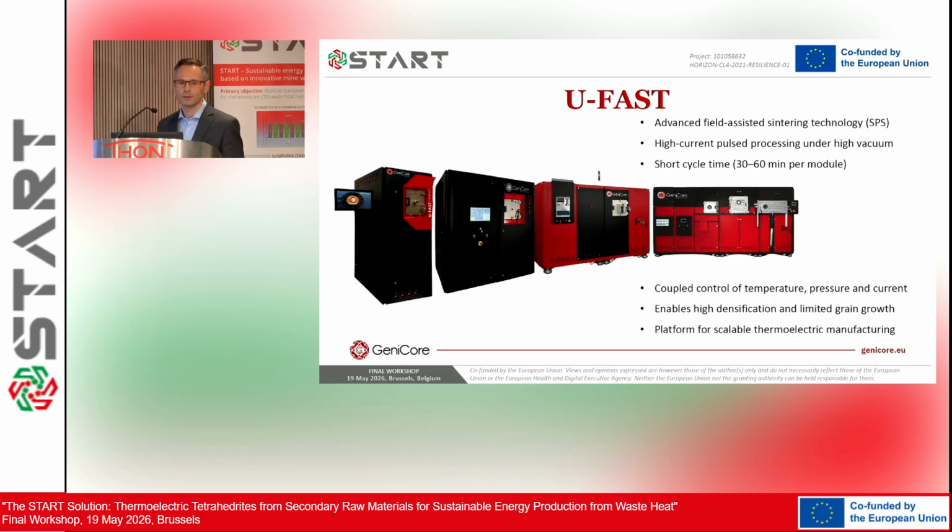A specific feature of this technology is quite short cycle time, very often below 1 hour, with annealing time of a few minutes at the sintering temperature. This technology enables high densification in the solid state, at relatively low sintering temperature, and with limited grain growth.